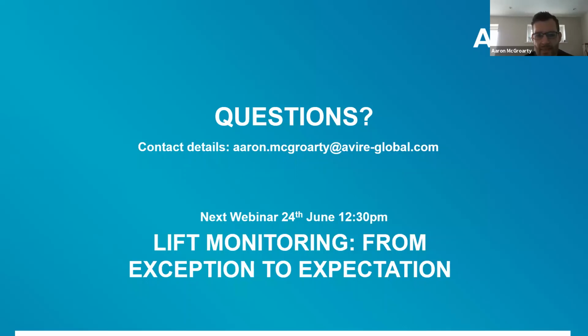I guess the second part of that question could be looking at how the system is fitted. To get video feed, you usually need to have an extra twisted pair or a VDSL connection or an Ethernet connection that allows for data to be transmitted from the car up into whatever cloud platform you have, which can be quite labor intensive. And we're actually seeing quite a lot of pushback from a lot of the maintenance companies in the US in terms of this being made active.